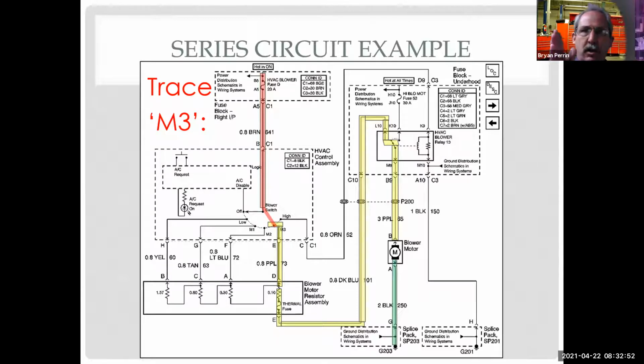If it works here, all the parts that work have to be good. So if over here, all the parts that were good in the first place still have to be good over here where it doesn't work. So I need to concentrate on the parts that are different. And that's that compare and eliminate we were kind of looking at with the lights on the car.